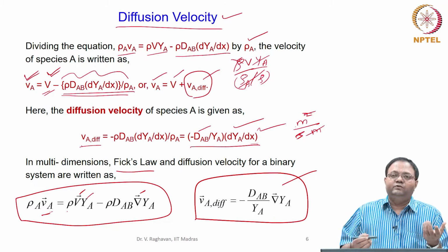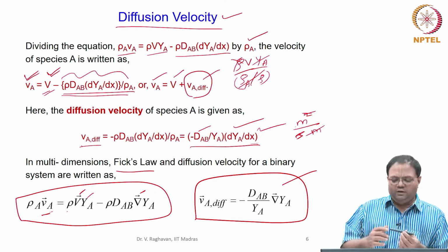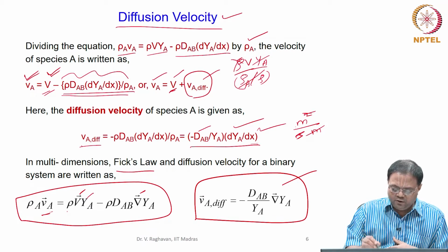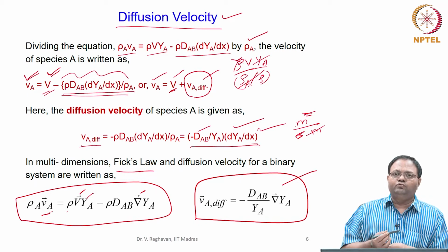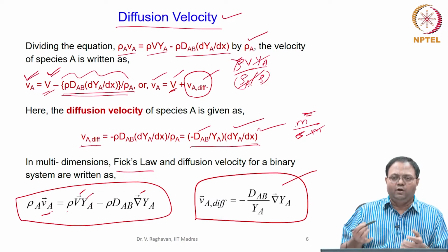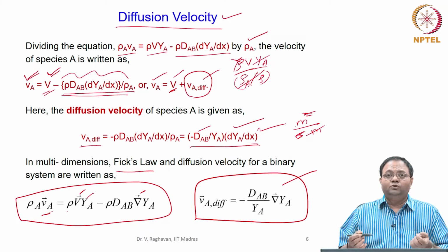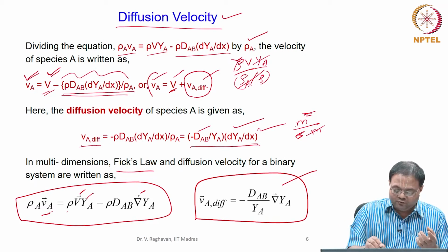The main thing is we first have to calculate the velocities. It is easy to calculate or measure the mixture velocity. You can solve the Navier-Stokes equations numerically to get the velocity, or if you want to measure it, you can use any methodology like a Pitot tube or PIV. The next challenge is that I need species velocity for conserving each species.